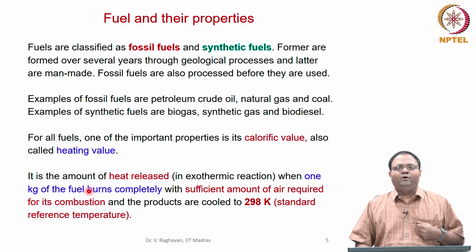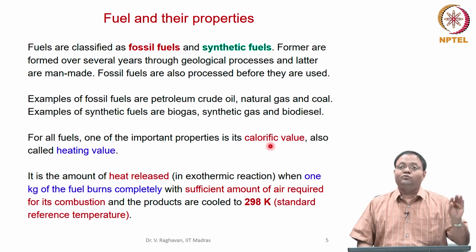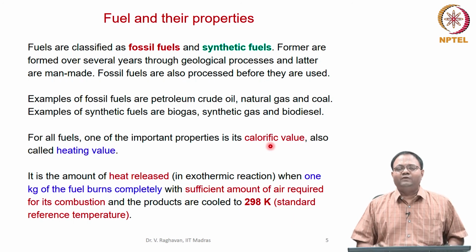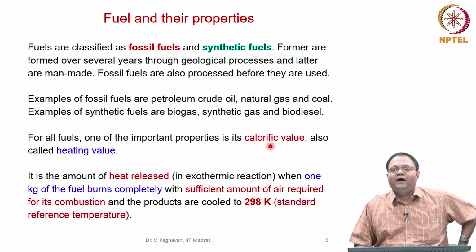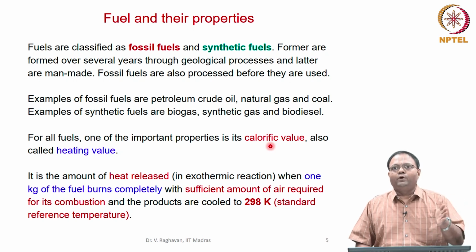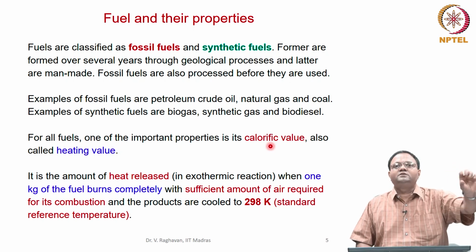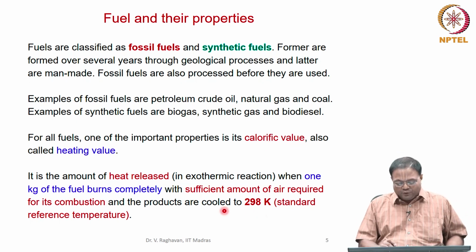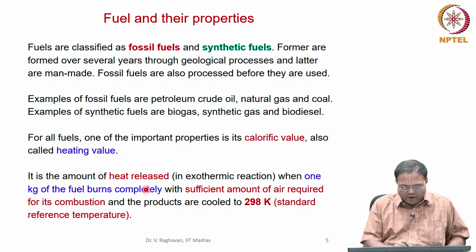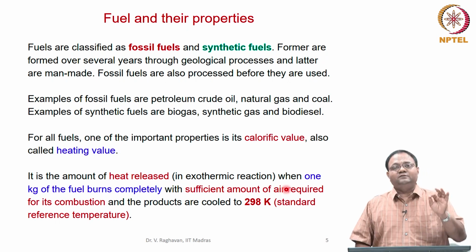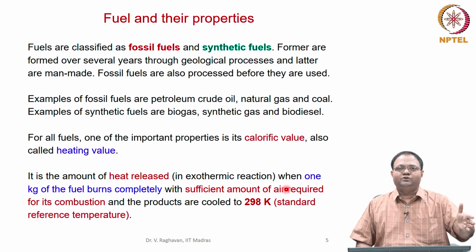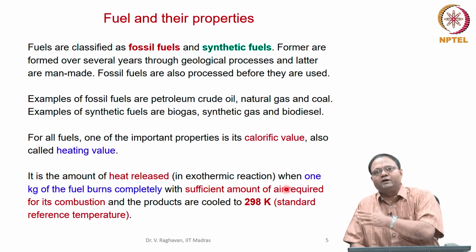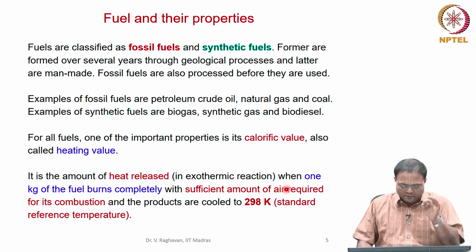Now when I design my power plant, I will use the calorific value, but I will also add an efficiency factor. If x kg of fuel is required to achieve the power of, say, 2 megawatts, I will burn x times 1.2, so that I will surely reach that power capacity. Now, when I say calorific value, these are all done in a standard condition. One can burn at a particular temperature and say this is the value I got, or one can burn in a different condition. So there should be some standard to specify the calorific value.